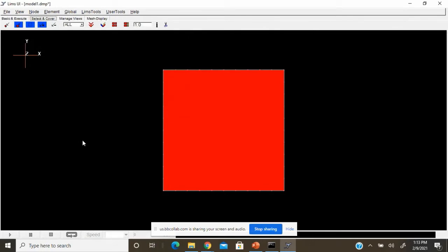We've assigned the inlet node for the resin injection. We've assigned the properties of the elements. Now we go ahead and assign the resin viscosity. So we'll set the viscosity to 0.2 Pascal second. So you click on OK.